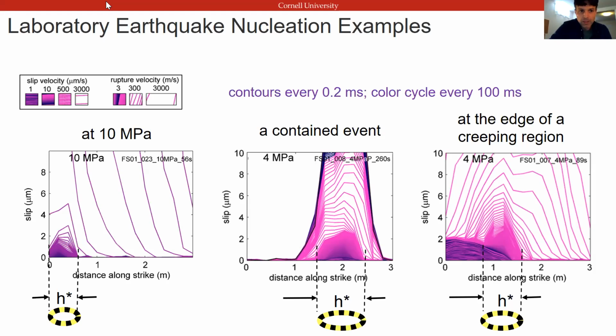If you don't have 1 meter, then the stick slip events will initiate because of the compliance of the loading frame and not because of the compliance of the rock. So the instability criterion will depend on your loading machine. That's why we have a 3 meter rock, right? Because we want to be able to see this initiation and get it to spontaneously rupture on its own, based on the elastic strain energy stored in the rock, not stored in the steel loading frame.